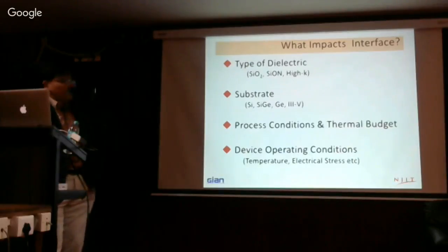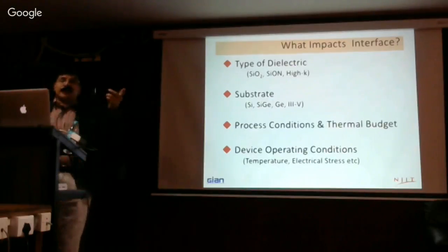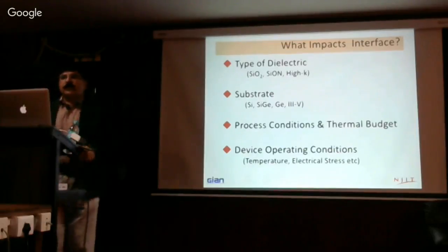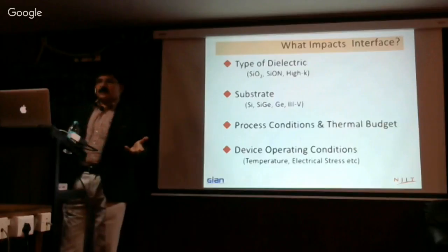And also, if you do the electrical stress, we'll discuss some of those. Then also it will change. Even the devices, when you make an inverter and run the device several cycles, you will see it will also shift. The flat band voltage will shift because the charge in the oxide changes.